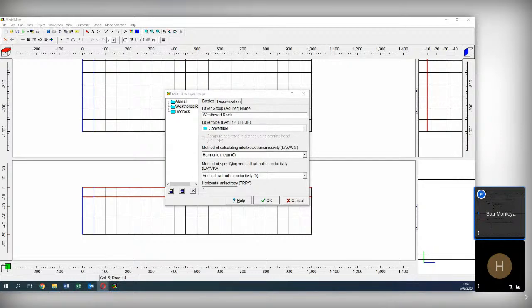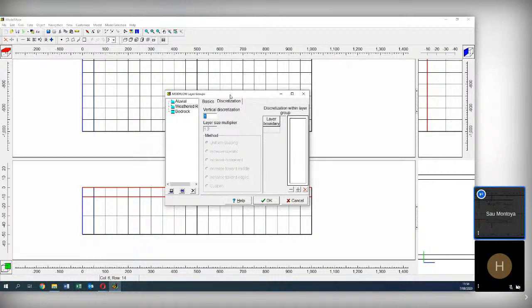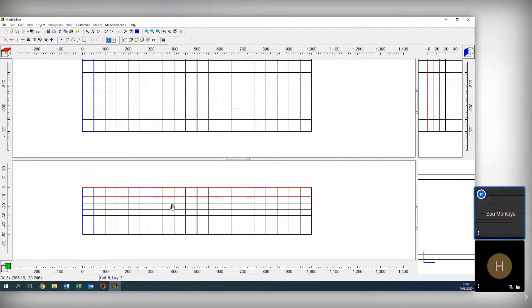Okay, some options that we have here is that we can split the layer as long as we want. For example, we can divide this into 3. If we type OK, our second layer will be divided by 3, Control Z. But I wanted the first layer to be divided by 3.